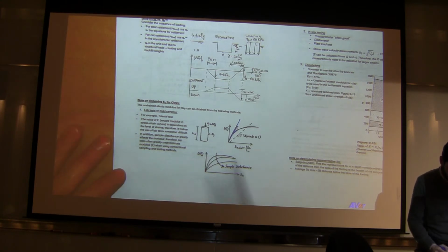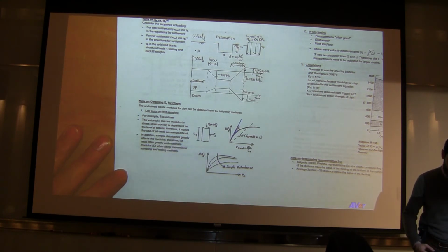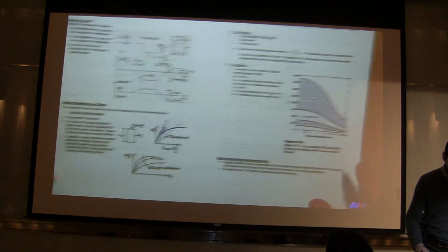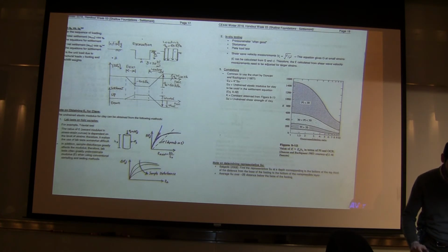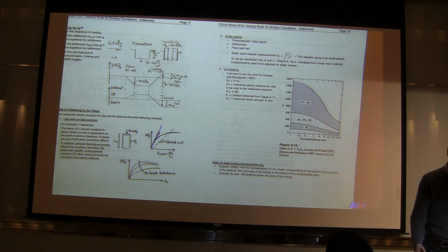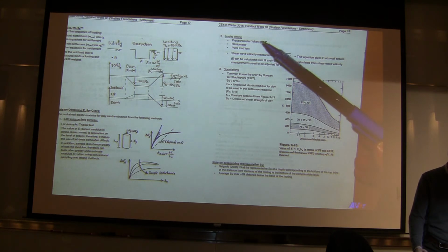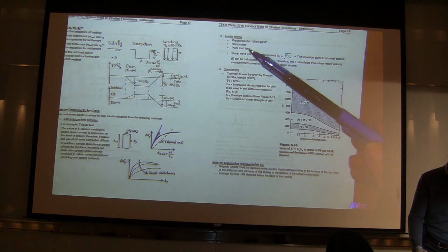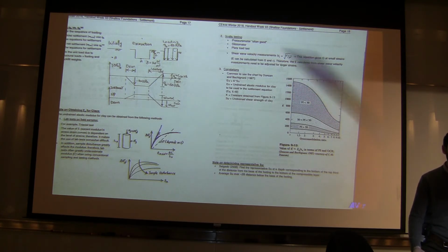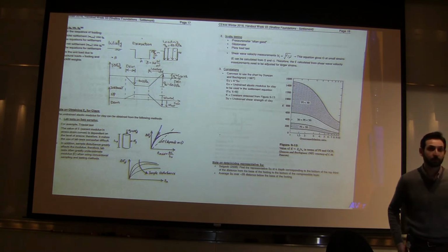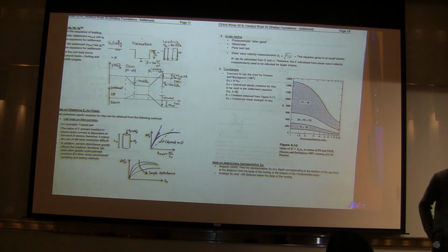So that's the lab test. Now let's go to page 18 for in situ tests. Same stuff. We have the in situ tests that we have. We have the pressuremeter, which tends to be a very good estimate. It tends to give you a very good estimate of elastic modulus in clays.